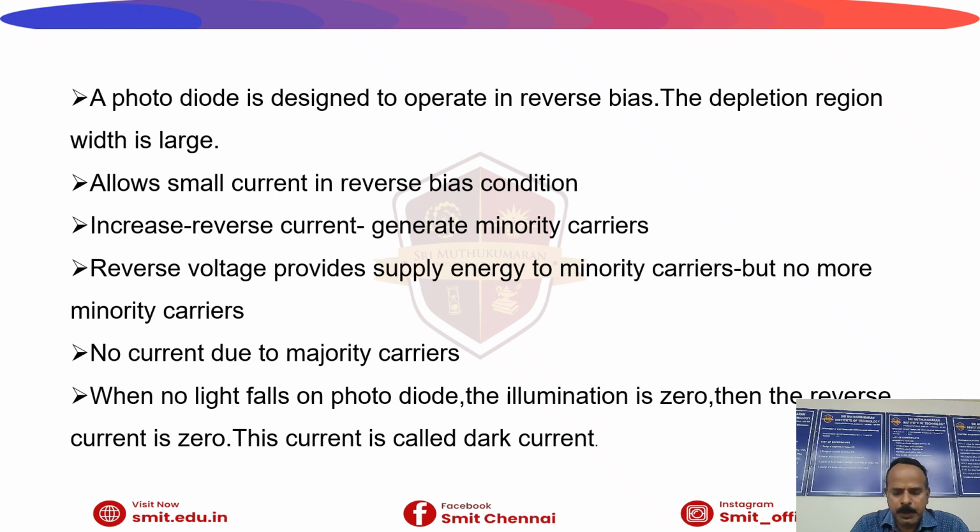A photodiode is constructed very similar to a p-n junction diode in many ways, but it is optimized for light absorption. It is designed with a wide diffusion region to improve the light sensitivity. When operated in reverse bias, the depletion region becomes very much wider. In the reverse bias, only a very small reverse current flows under normal conditions.